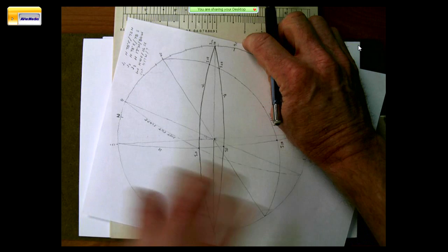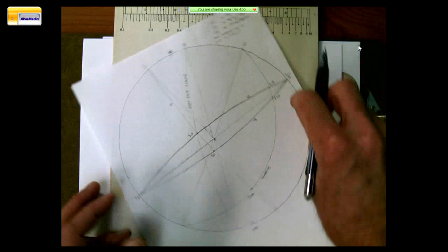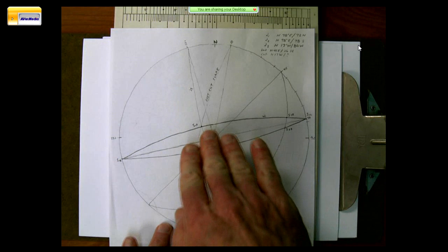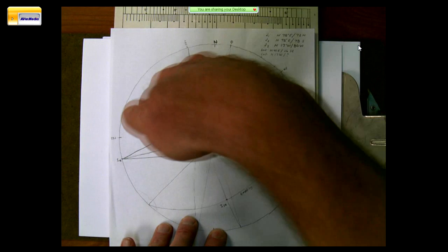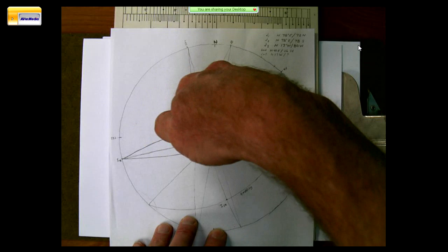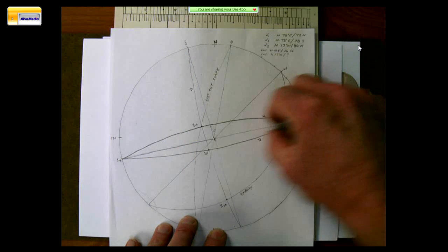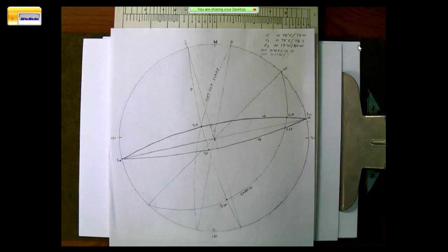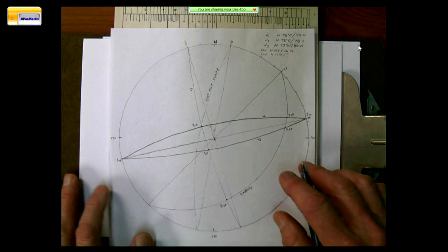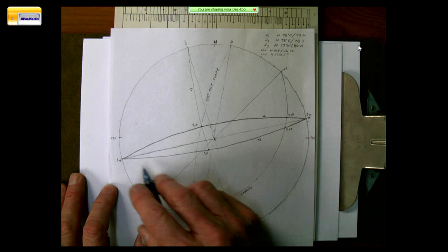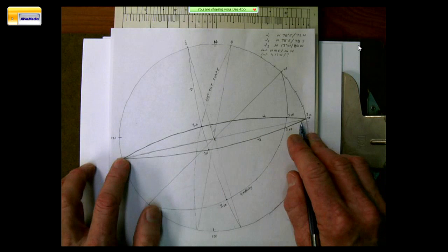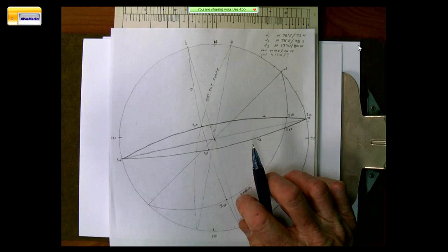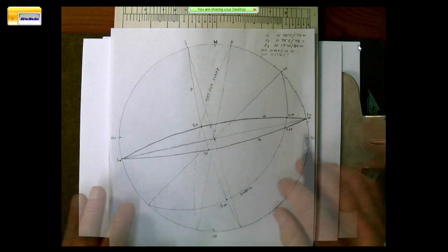But that's the average. So now we rotate back to north, and what we see is we have one set dipping very steeply to the north and another set dipping even more steeply to the south. So that's going to be a very tight sliver wedge posed by those two where those two meet. And they're not going to be a whole lot of problem because their line of intersection is horizontal. So they're not going to come spilling out of a highway cut on us because they have the same strike.